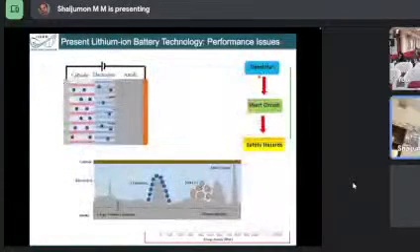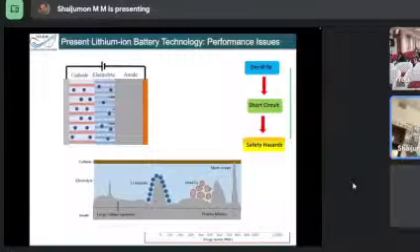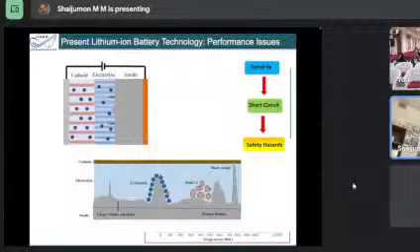I wanted to tell you that when you're using liquid electrolyte, there is something called dendrites. The lithium will have an overshoot growth. Some sort of needle-like structures will form, because of the reaction products formed, since we are using the electrolyte. These needle-like structures, or dendrites, will pierce through the electrolyte and the separator. It touches the cathode, and of course it short circuits, right?